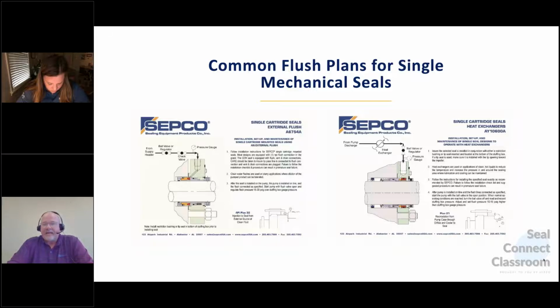There are even special design mechanical seals that can be designed to handle higher pressures and equipment movement and that sort of thing. But the basic face lubrication principles, whether it's a custom seal or an off-the-shelf, out-of-the-box standard ANSI seal, the face lubrication is what we're going to be talking about in the next few minutes. And that's what's critical, to have enough pressure to lubricate the face and have something cool and clean to lubricate the face. You can go ahead and a clearance change.